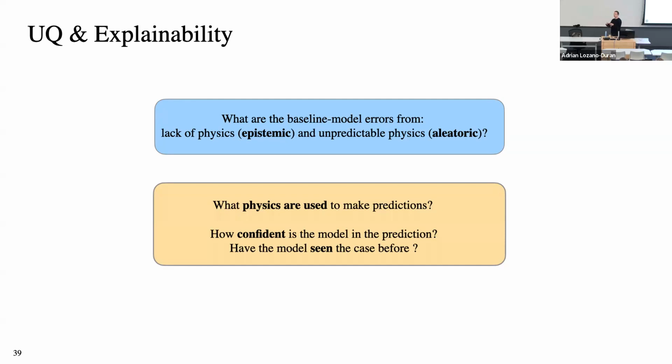I would need to increase the stencil of the model, which will increase the complexity. So for now, those I give up. What my model would do is give an average of the different options that it has, and I live with that. But I know when that's happening. I can actually report that and say, okay, this region of the aircraft, in this corner, there is high aleatoric error. It means that my model cannot distinguish which building block it has to use. It's ambiguous.